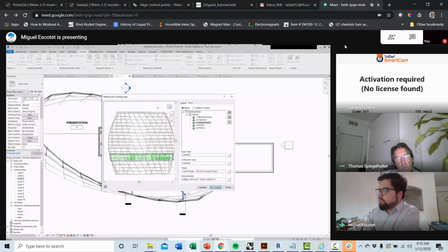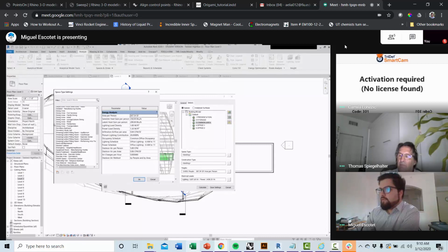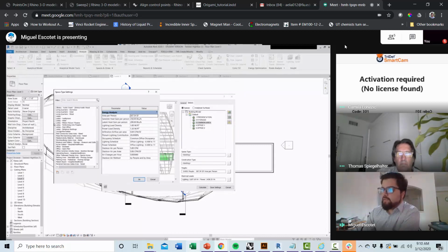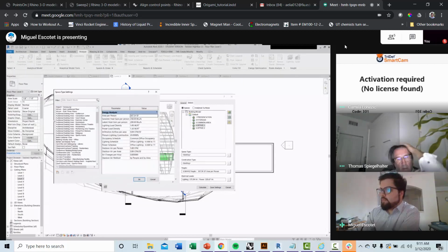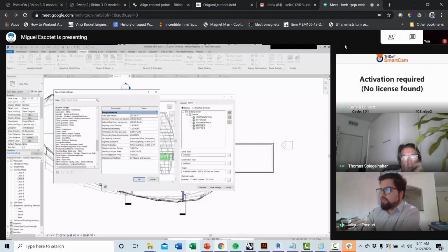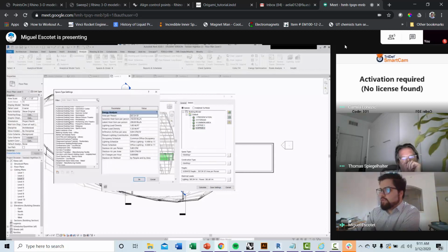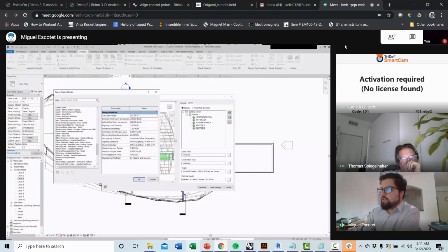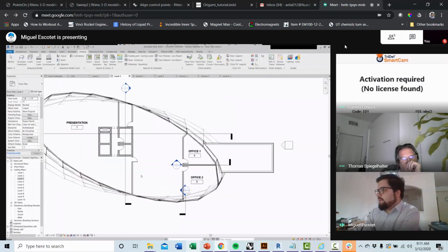To wrap this up a little bit, we have the common area, building type, office. If you see here, it's very specific. So you can have office enclosed and office open plan. So we can get to the open plan, select it, updated. Then we can go to space type here and look for office, which is going to be enclosed. We have different spaces for different situations and different conditions. And now that we do it, we can save settings.